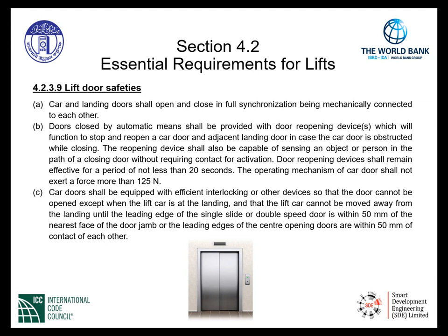The reopening device shall also be capable of sensing an object or person in the path of a closing door without requiring contact for activation. Door reopening devices shall remain effective for a period of not less than 20 seconds. The operating mechanism of car door shall not exert a force of more than 125 newtons.